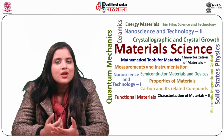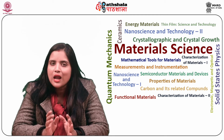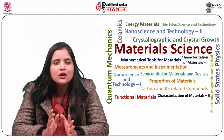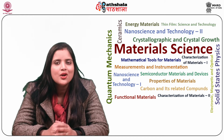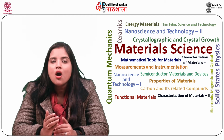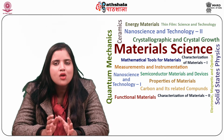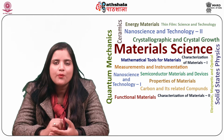The inert gas evaporation condensation processing, wherein nanostructured materials are produced by the evaporation of a metal source in an inert gas, is an extensively employed technique to synthesize very fine metallic particles or nanoparticles since the 1930s. This synthesis protocol has been followed for producing crystalline nanoparticles in powder form.